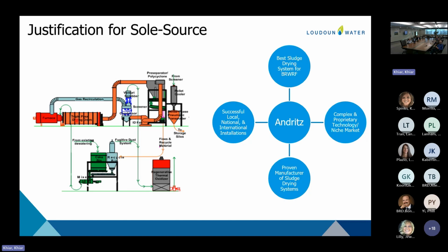And then the combination of the gas stream and the pellets come out. They go to these separation structures here. There's a pre-separator, a plate separator, and then also a sort of polishing separator, the polycyclone. The pellets are collected or separated out in these two. And then there's a shaker deck or a screener that classifies the pellets.